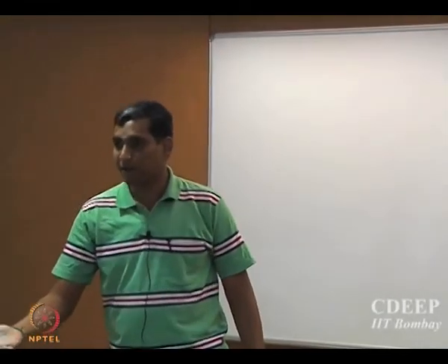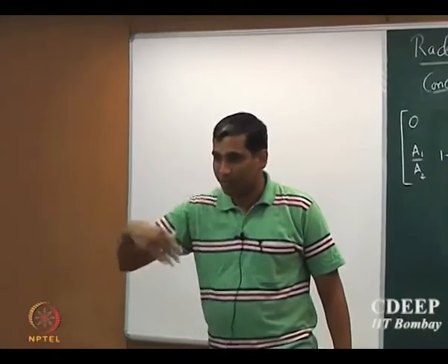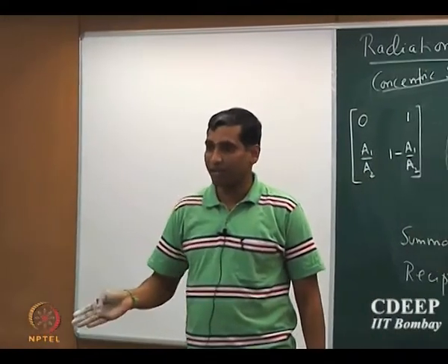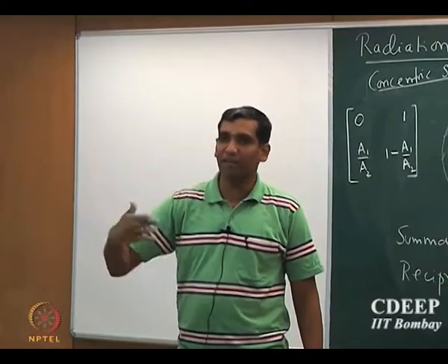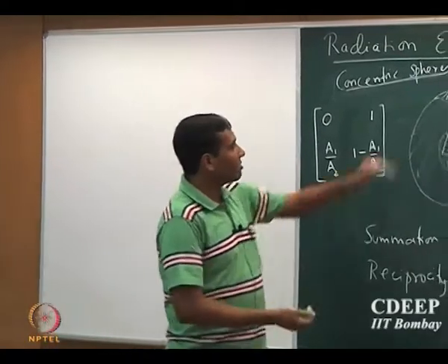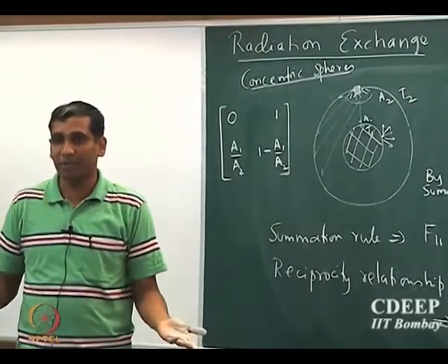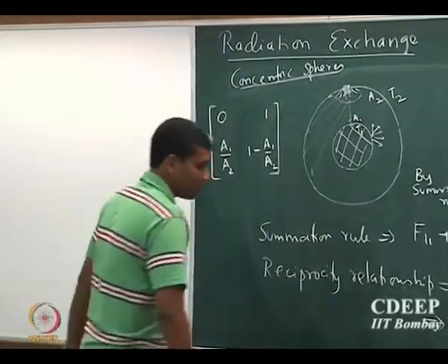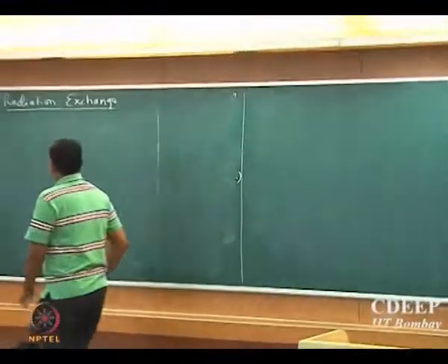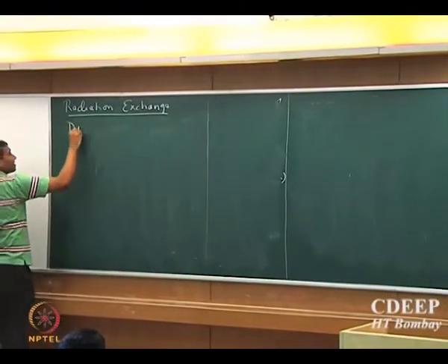It could be. So for example, you could paint with different colors and you could change the emissivity. Note that emissivity is a surface property. So if you change the properties of some locations of the surface, you're going to change the radiation properties. Alright, so next we are going to look at divided surfaces.